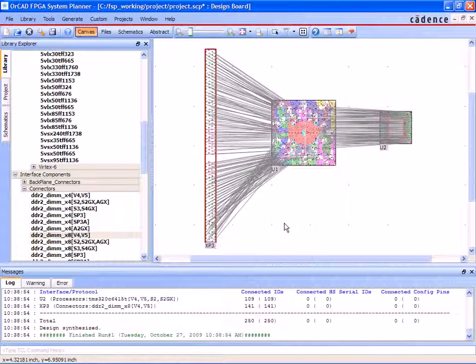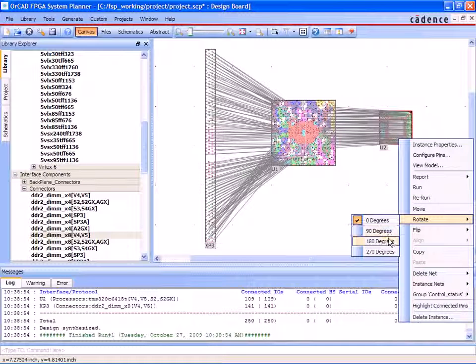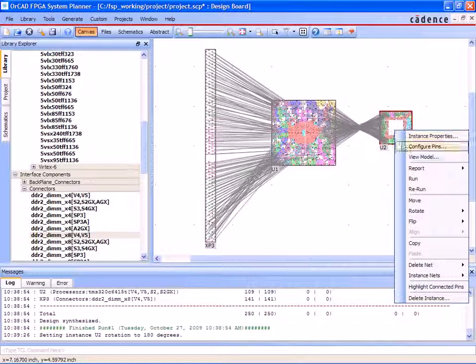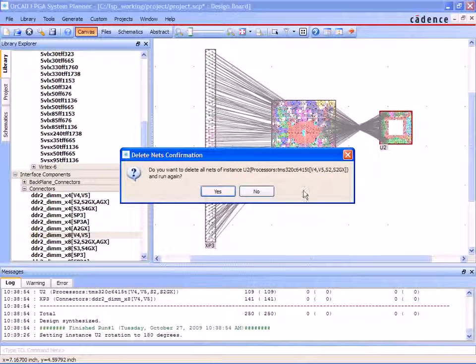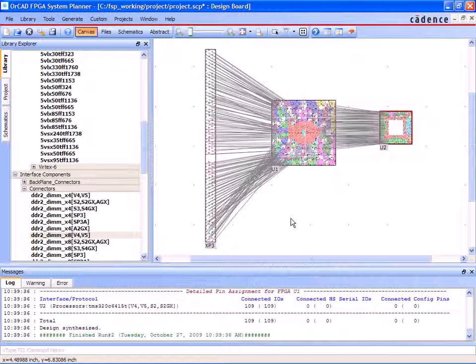As you can see, the connections, which are DRC accurate, were created very quickly. FSP has, in real time, synthesized a set of FPGA pin assignments which simultaneously meet the needs of both the FPGA designer and the PCB designer. The ability for FSP to wire up the design so rapidly allows designers to explore the architectural trade-offs both with regards to device selection and component placement. For example, the DSP can be easily rotated and its FPGA connections resynthesized. To do this with existing techniques would require hours of rework and close communication across the entire design team.